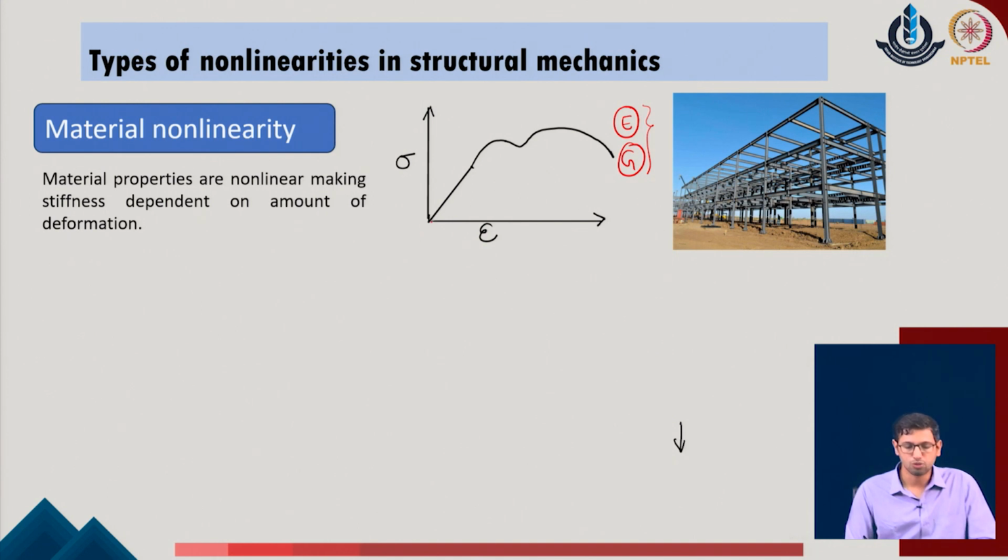As a simple material response which we have shown over here, the material follows a simple proportionality limit up to a certain point, beyond which the system moves into a range where it is no longer following the proportionality limit of the given system, which means that the linear relationship holds true up to a certain point, beyond which the material goes into the non-linearity, and at a certain point the system yields and moves into continuous deformation, which is the state where the system has undergone a plastic response, and the system will now have a material response which will no longer be defined by the constant value of the elastic modulus of the given system.